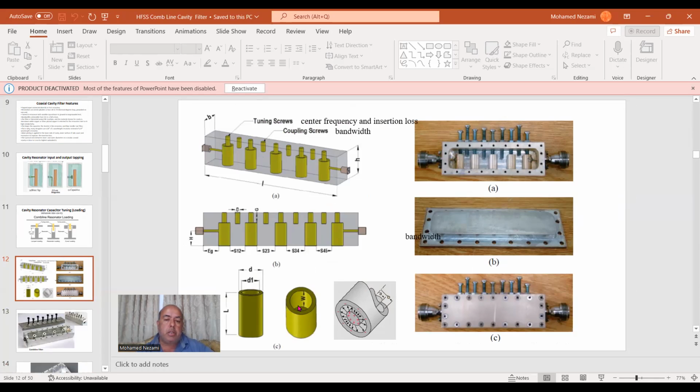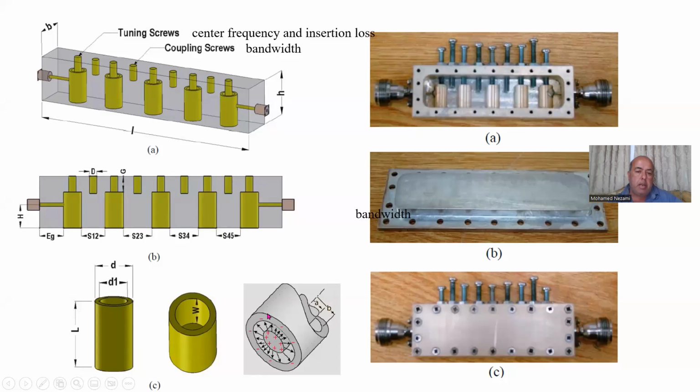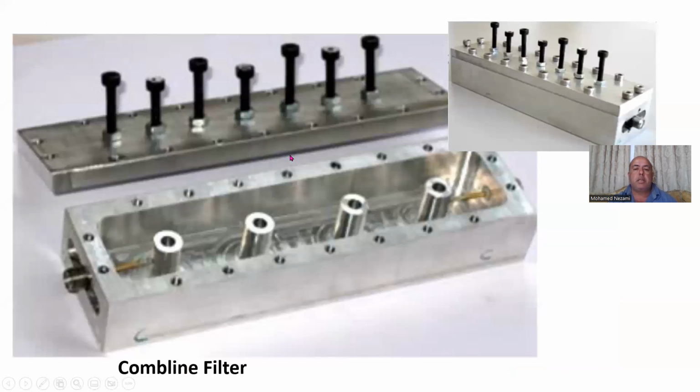In this construction, we utilize this tuning screw in here. There's a groove inside the resonator, and this tuning screw goes into this and acts, as shown right here, as a capacitor filter. This is a coaxial capacitor where the charges are stored between the inner and outer shield. The depth of how deep you can go into this controls the capacitance. And this is how physically it's done. You can see the groove is here, and so this screw just goes in and out.